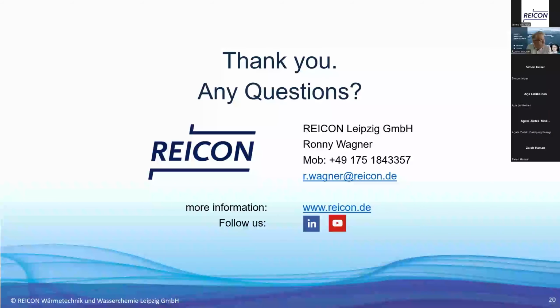Yeah. So the thing with the temperature, so all the standards are referring to a temperature of 25 degrees. So of course, as higher the temperature is, this can be an issue with the analytics, and we strongly recommend to have a sample cooler, because all other values also need a cooled sample, whether it's pH or conductivity. It's all referring to 25 degrees Celsius.